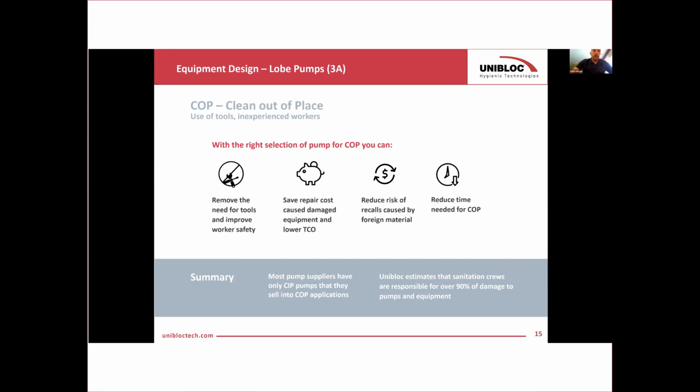And I want to highlight that most of the lobe pump manufacturers have one design pump, and that is a CIP design pump with a lot of O-rings and elastomers to meet that standard. And that is then being used in COP applications, but that doesn't have to be the case. If you can find a pump that is actually designed for COP, the better for you.